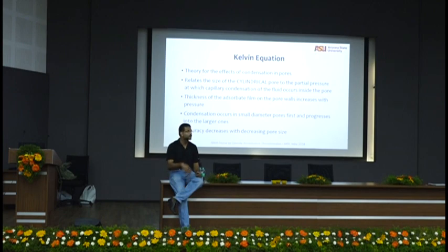So for example, somebody tells you, I want a clinker factor of 80%, and somebody gave you a concrete with only 50%. If you hydrate for exactly the same time and compare those, you will know which one has a higher reaction product. OPC, CSH products will typically have a much higher surface area than unreacted fly ash. Now, if the fly ash also reacts and forms secondary CSH, it becomes very difficult. But at early age, before 28 days, if you want to figure out the difference in cement content, this way can be used.